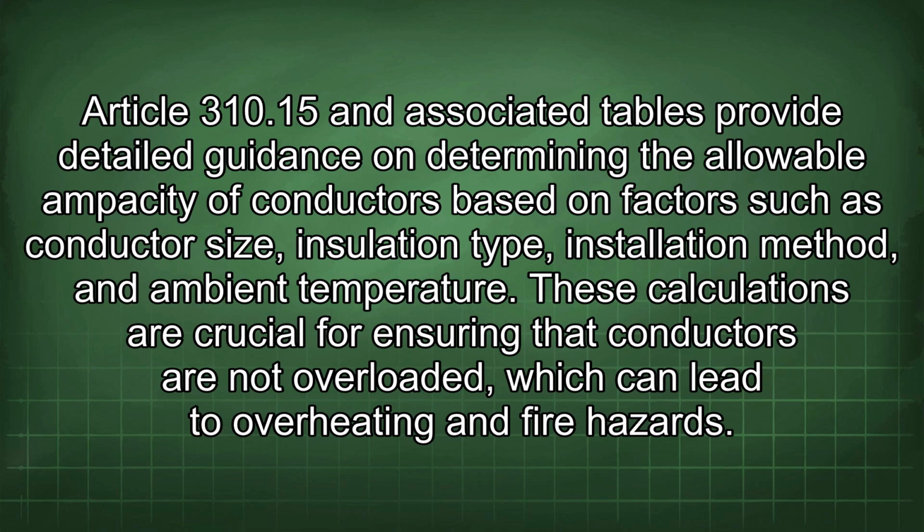Article 310.15 and associated tables provide detailed guidance on determining the allowable ampacity of conductors based on factors such as conductor size, insulation type, installation method, and ambient temperature. These calculations are crucial for ensuring that conductors are not overloaded, which can lead to overheating and fire hazards.